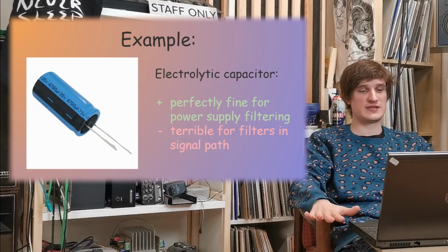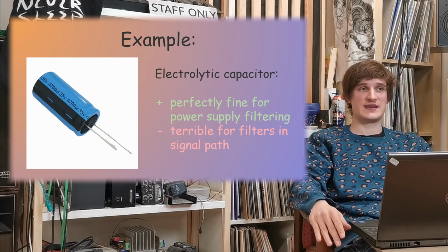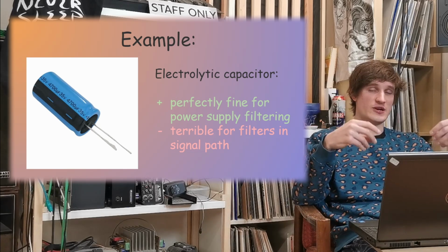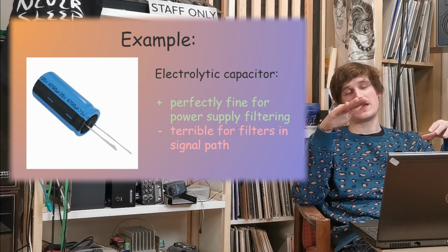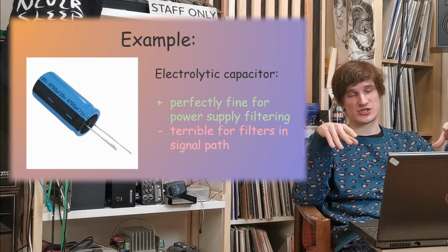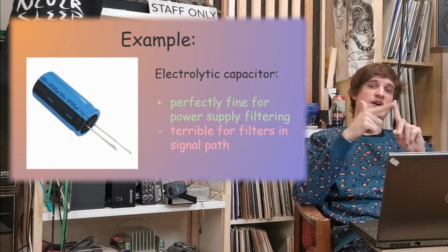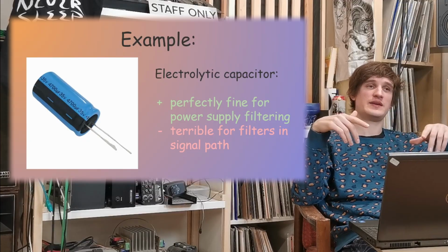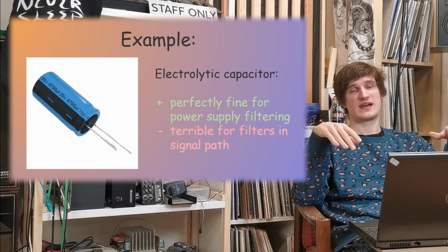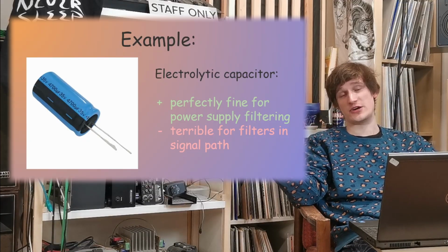But yes, it's proven that electrolytic capacitors are not linear, so in filtering applications they would be terrible because of non-linearity. And the other thing is that electrolytic capacitors mainly have very wide tolerance.